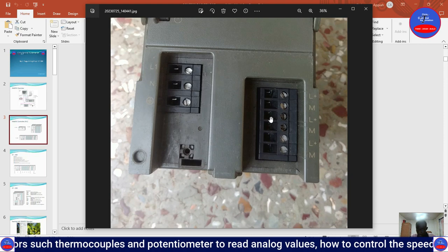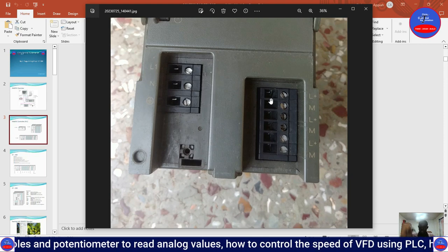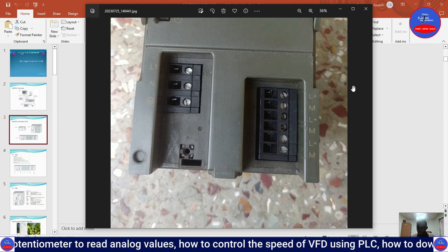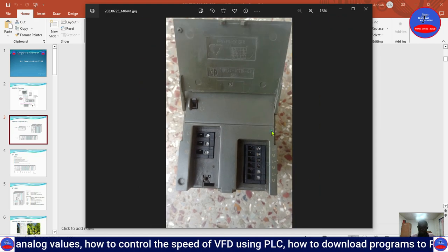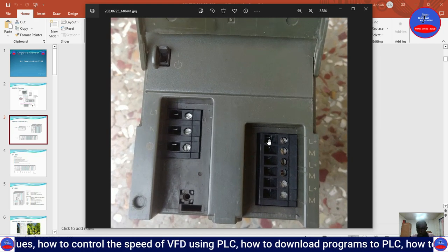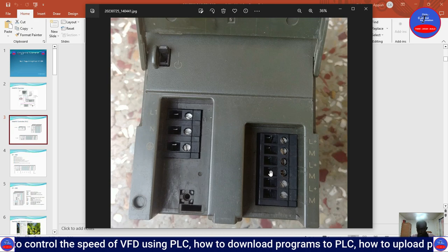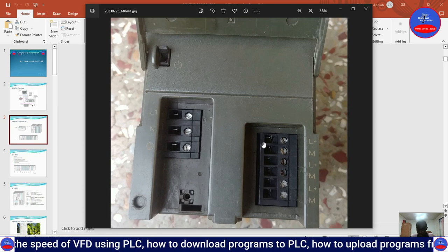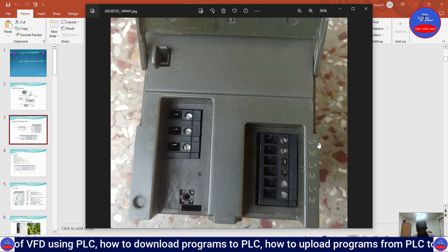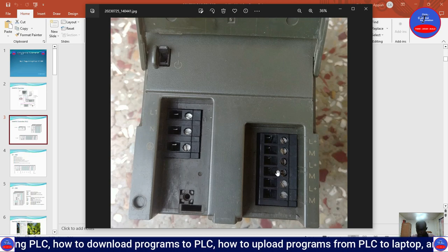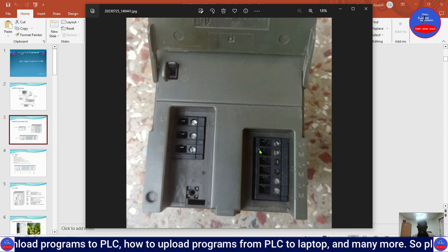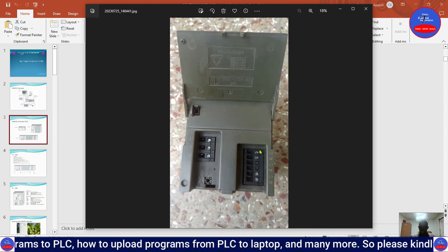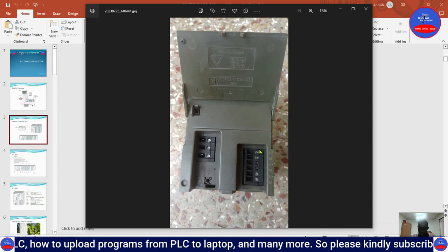They are all the same voltages, just that they've joined them, so that in case you want to use 24 for some other work, you can pick it from here or any other place. So this is 1, this is 2, and then 3. So positive 24, negative 24, positive 24, negative 24, positive 24, negative 24. All right, so now from here we are going to the CPU.